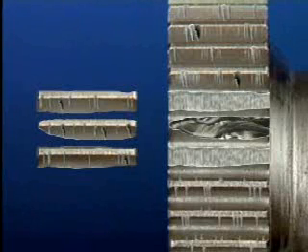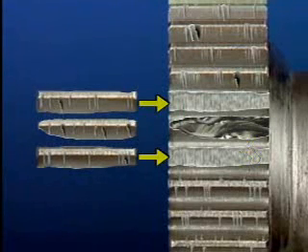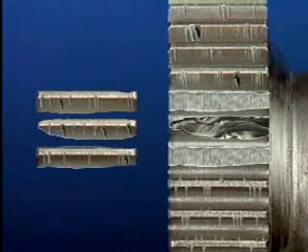However, when you discover a failure that was caused by an external overload, you'll have to investigate the problem further. A first look at this damaged gear shows that a tooth was broken due to fatigue failure, and that the adjoining teeth broke due to overload. It looks very similar to the gear that failed from an internal overload. However, an inspection of the crown of the tooth, which broke from fatigue, reveals that it was deformed before it broke.